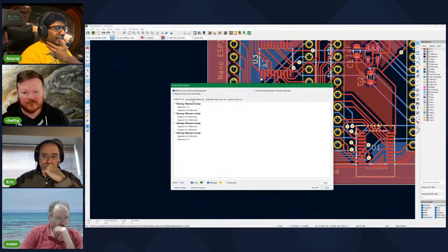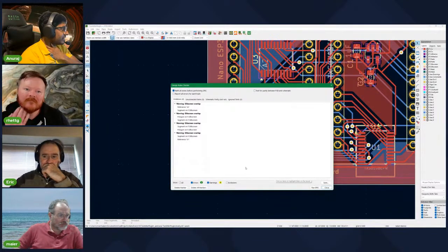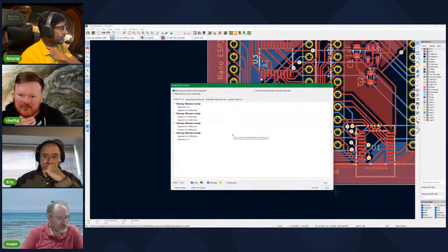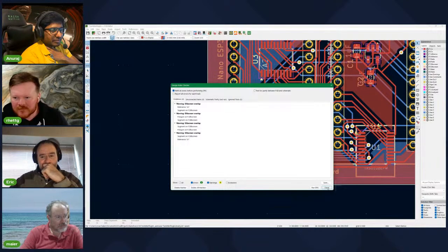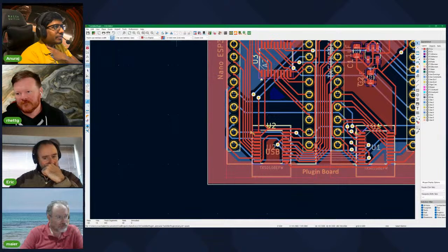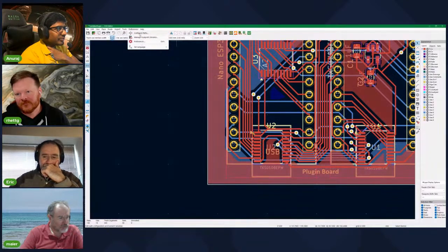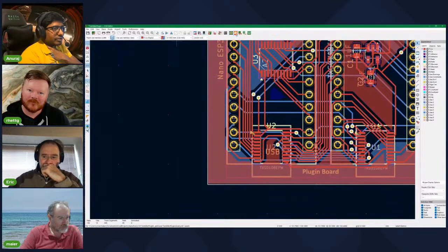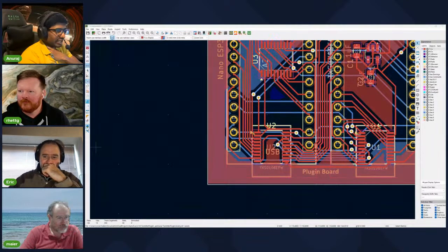If there are some major electrical violations, you need to run the DRC after the auto routing and then manually route those lines. After you are done with this, you need to go to the plugin. Each of these manufacturers has their own plugins.